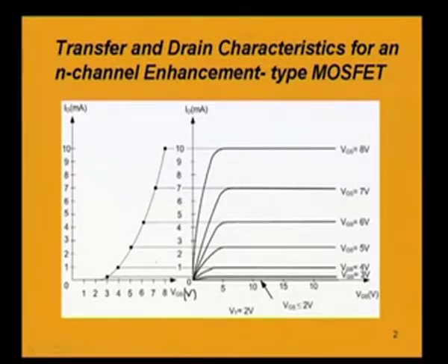Now, for example, VGS is equal to 3 volt, this is the saturation current. So we extend it and this current is intersecting the VGS 3 volt at this point. So this is one point. Obviously, the earlier point is 0 current and 2 volt, because for VGS 2 volt, which is the threshold voltage, the drain current is 0. So 2 volt and 0 milliampere drain current, this is one point actually. It will be starting from this point and it will be continuing.